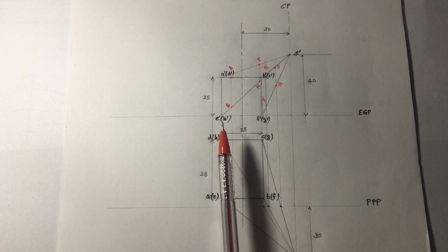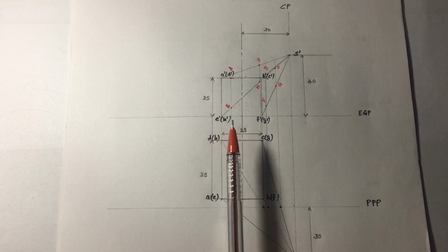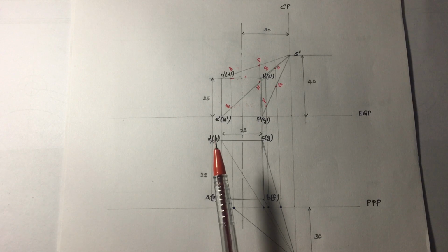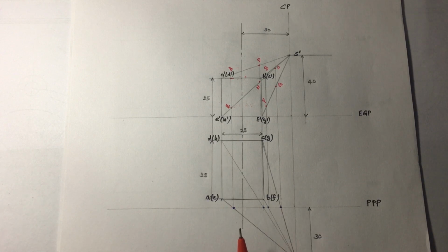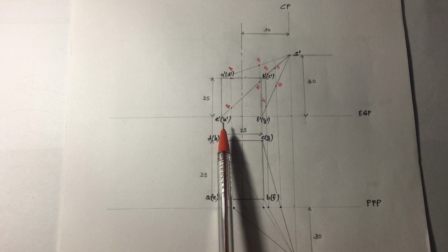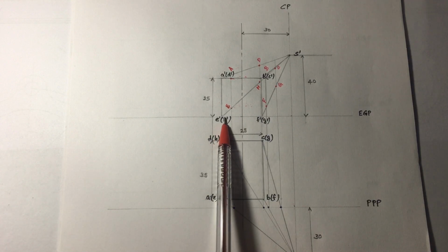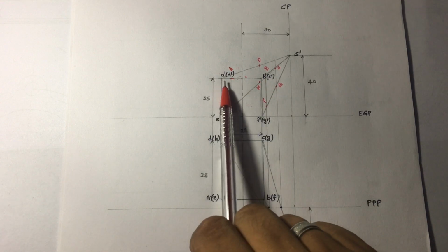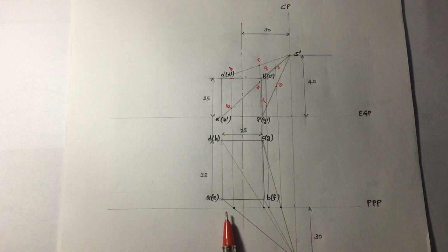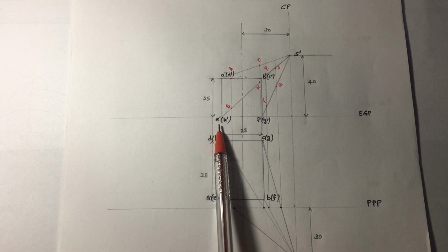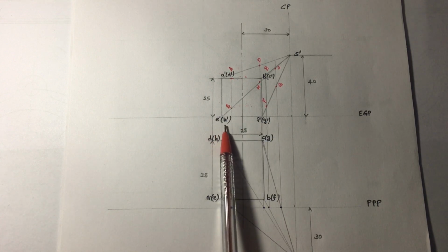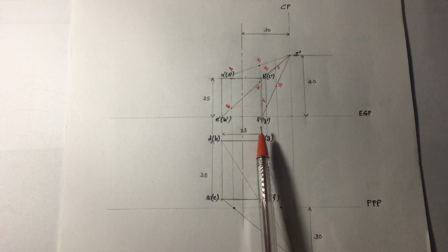Okay, so this has to be marked, and then you have to go into step number 4, which is the front view of the object. The front view of the object is a square just because the square face is parallel to the picture plane. Okay, so here a square will be coming, with the dimension 25. So you have to mark it correspondingly. ABCD edges will be coming in the top, and the EFGH edges, as it is coming in the brackets in the top view, those edges will be coming in the bottom. Okay, so you have to mark E dash, bracket H dash, and F dash, and in brackets G dash.